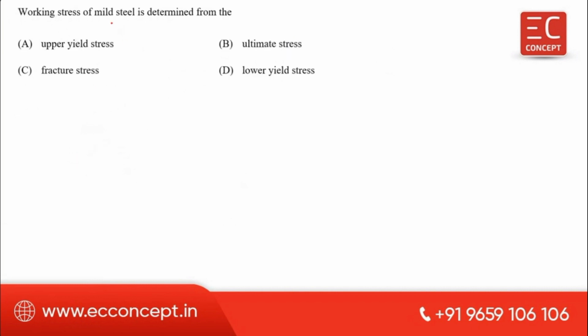Now, the working stress of mild steel is determined from the upper yield stress, ultimate stress, fracture stress, or lower yield stress. So the answer for this question is lower yield stress. Based on this lower yield stress only, we determine the working stress of the mild steel.